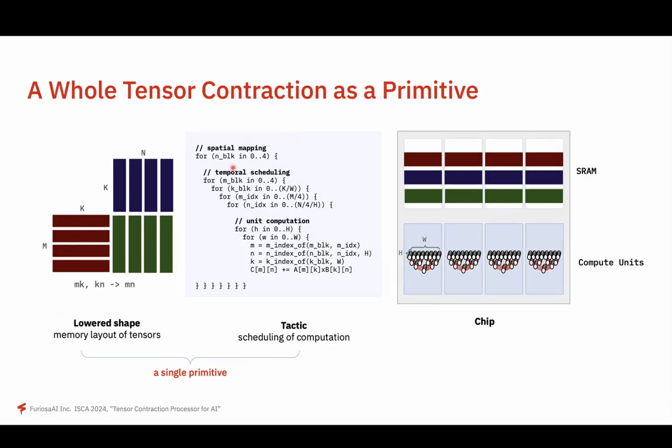So in such a case, the dot product based accelerator will be useful. This is one example of a dot product based accelerator. Here we have multiple dot product engines, so we can do 8 dot product operations in parallel inside of this. Each dot product will do a dot product of 2 vectors having double dimension. So here we have 4 dot product units, and they have their own local memory.